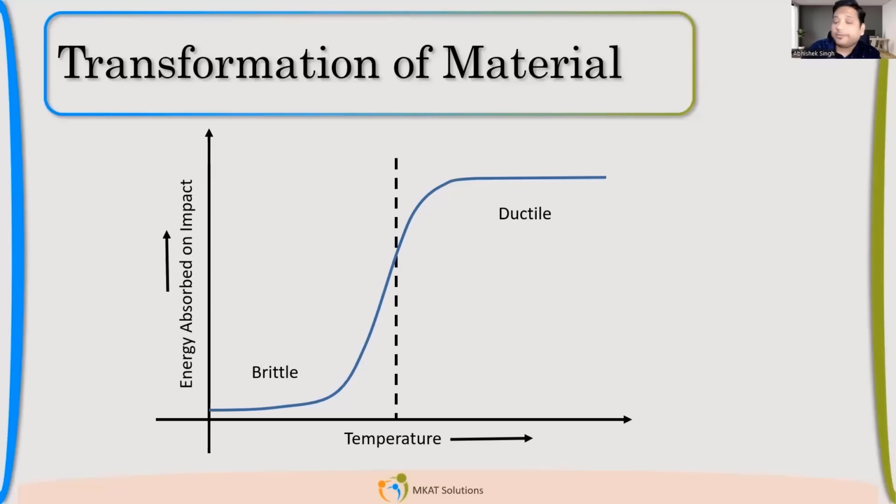Now, if it is that simple, then why are we going to find the MDMT? What is the reason for bringing MDMT into the picture? If we can just do impact testing and find the energy... It's not always feasible. Okay, great. The reason is that doing impact testing all the time will be really costly and time consuming.